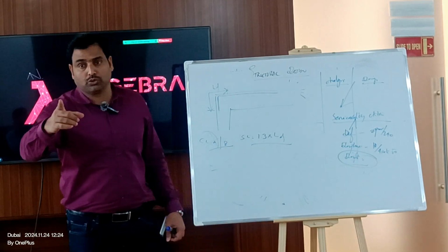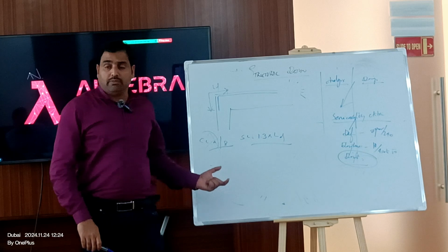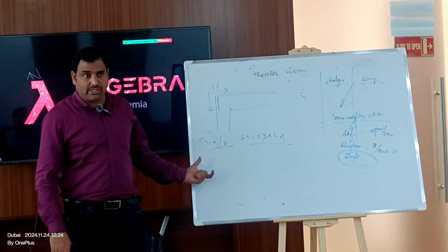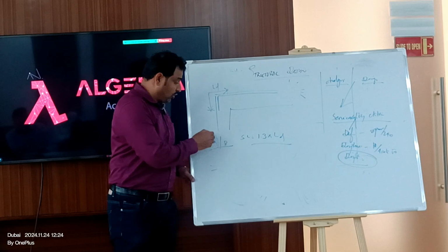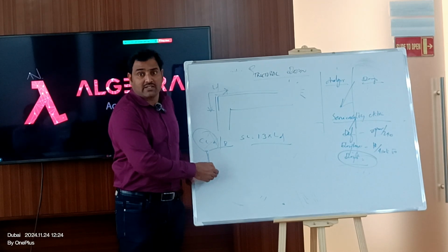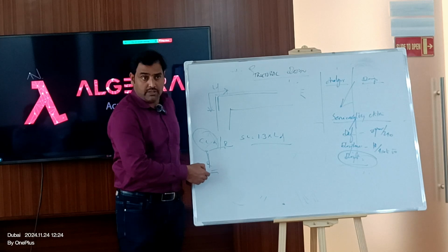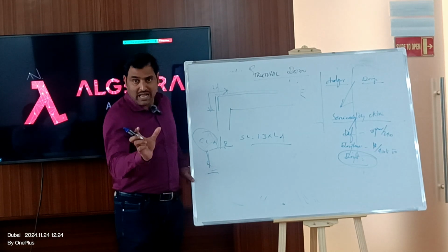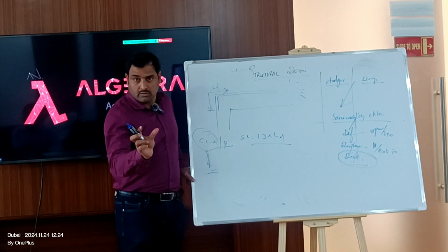Now coming back to your question: same rebar, but where exactly you require less bonding and less load interaction, you will use the class A category. In class A, the lap splice is less than class B. Only the lap ratio is different.